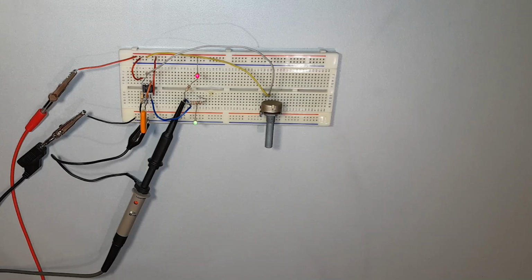So now we're going to play with this a little bit further. So I'm going to adjust RA like this, and I'm going to bring the mark to space ratio back onto the screen, and we can see here now we are 10 squares fully across. I've moved RA to 5 kiloohms, so I've turned it fully clockwise, so it's fully in circuit. So it's 5 kiloohms for RA, and RB is 100 kiloohms. So the mark is 5.2 squares, and the space is 4.8 squares across there.